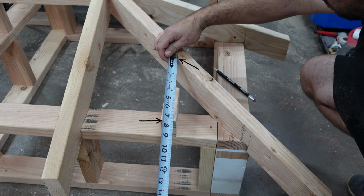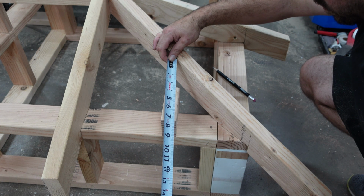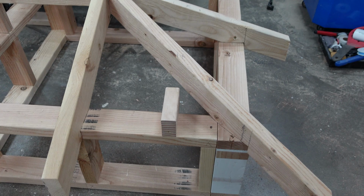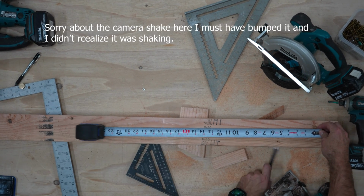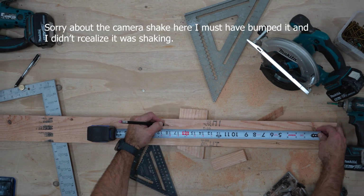On the hip, we always want the X that marks where our jack rafter goes lower than the layout line. This is because it is a lot easier to measure the long point on the jack rafter. To be more specific, the point we are measuring is on a compound bevel, so we are finding the long of a long point. I covered long point and short points in a different video, so I won't go over it again, but it's pretty self-explanatory.